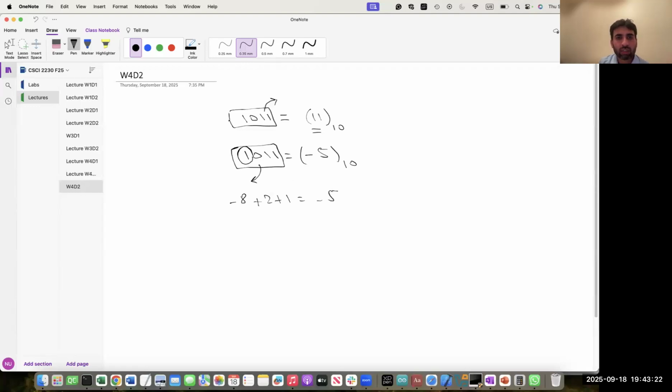So when you are dealing with unsigned numbers, where you consider that your most significant bit is not representing the sign and has positive weight, and you want to compare them and then take a branch based on the comparison, then you can use instructions like branch same or higher, branch low, branch equal, branch not equal, and so on, right? I'm not writing all of them.